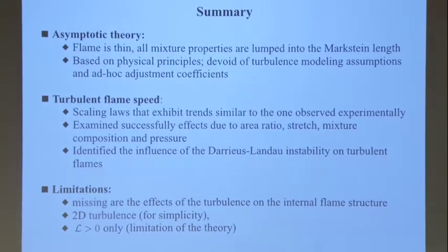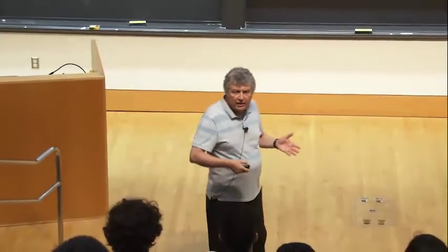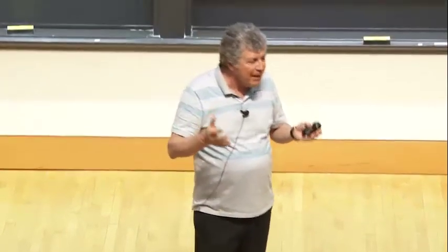Also, we have so far discussed 2D, and frankly, people in turbulence tell you that there is no such thing as two-dimensional turbulence, which is probably correct. But there are a lot of things that we can learn from here as we move into 3D. There are things, for example, like vortex stretching, that exist in turbulence but not in 2D. And the question is, how important are these? When you do a 2D calculation, and that's an applied mathematics view, then tomorrow you do 3D, and you look at the effect of vortex stretching, you will understand exactly what vortex stretching does. Without that comparison, it's only speculation.